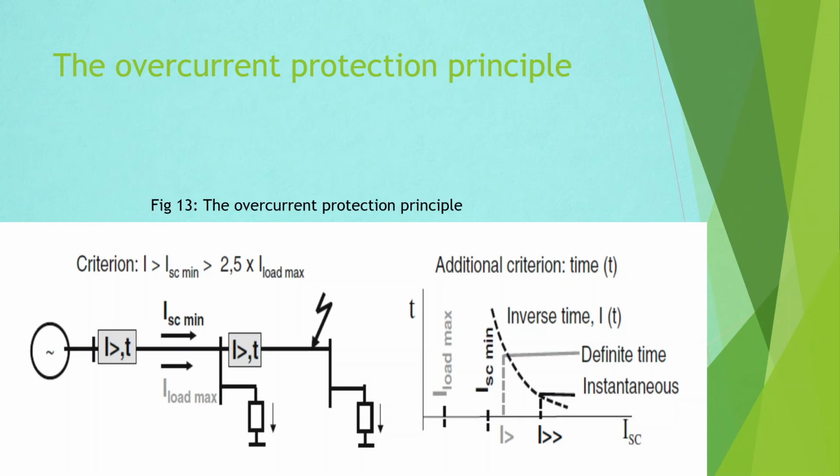A busbar fault may cause a trip of the whole or part of the substation with all connected transformers and lines. The sum of complex currents considering the direction results in a difference current that will be strictly calculated separately for all electrically autonomous busbar segments. In case of a busbar segment fault, all circuit breakers of the connected feeders will be tripped. The busbar protection shall decide to trip within 8 to 12 milliseconds to avoid equipment damage.